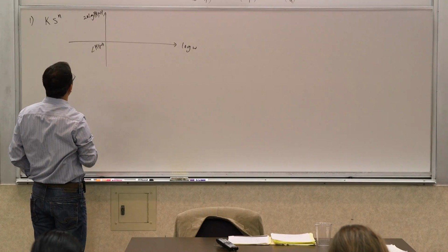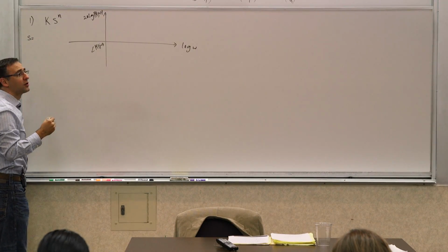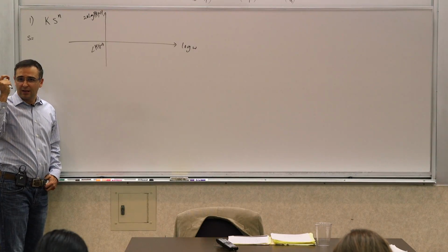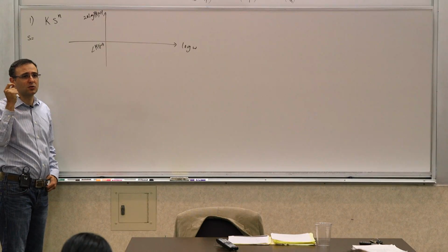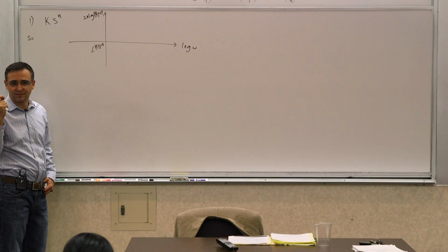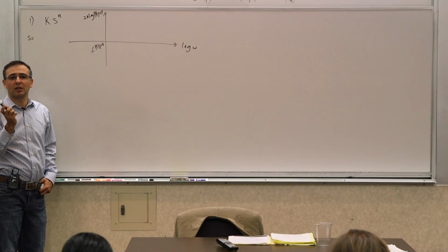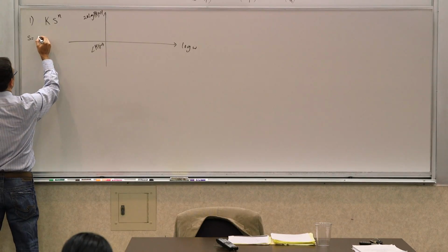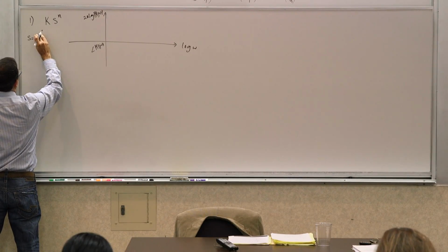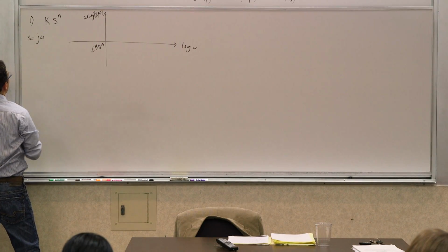Right? So how does that look? Well, let's look at it. Whenever you're looking at Bode plots, you're looking at specific kinds of s. You're looking at sines and cosines, which corresponds to s being j omega. More accurately, you're looking at unity magnitude exponentials, e to the j something, as stimuli, which can be written as sums of sines and cosines. So s equals j omega.